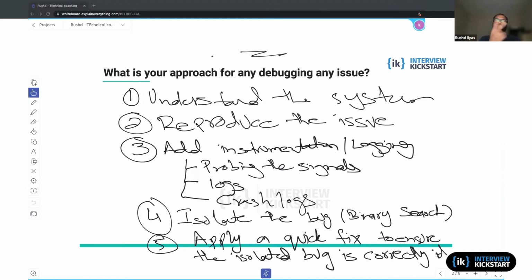When you reset and boot up, you basically read it from the RAM, or if you already stored it in the flash, that's good. If you didn't store it in the flash because you wanted to reset instantly, you read that information from the RAM and write it to non-volatile memory. When you get the chance, you transfer it over any serial or wireless communication, or write it to a memory card, whatever the interface is. Eventually, hopefully, the app or whatever your device connects to can transfer that information over the internet to the company, if it's an IoT device.